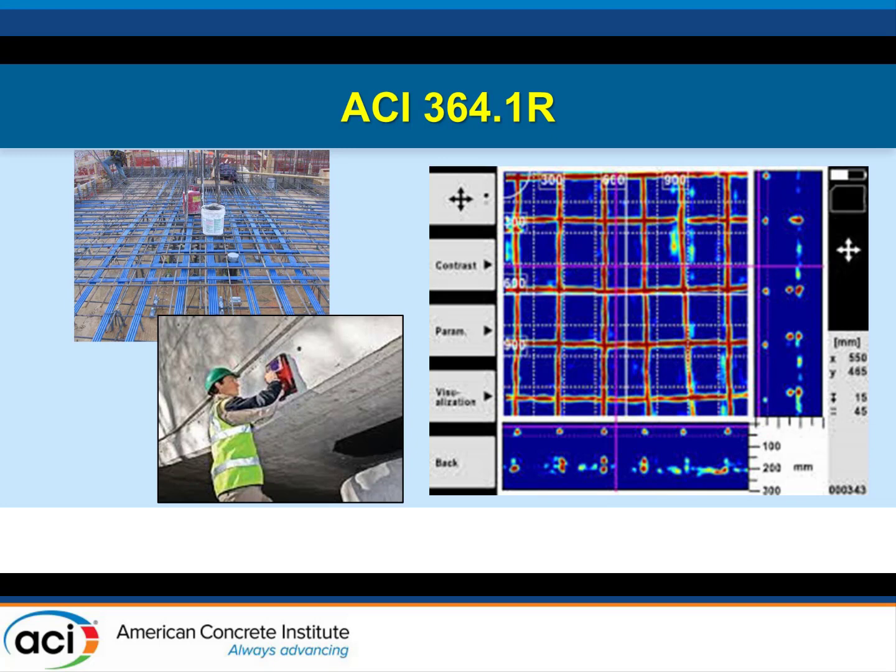I think the thing I want to point out is whereas it's good at locating it, it will also tell you information very accurately, like what the depth of cover is, which becomes a thing. It will not tell you to a too high degree of accuracy the exact size of the reinforcing, and unfortunately what it won't tell you is what's the condition of the reinforcing inside.